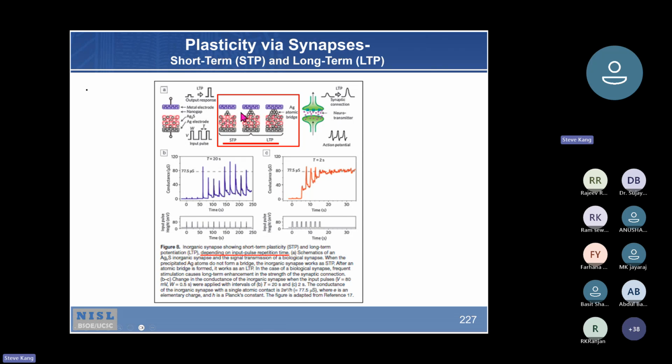And this graph shows a memristor, and whether your filament is fully connected, like here, or not connected, and then weakly connected, almost connected. So when it is in an unstable state here, it's short-term learning, short-term plasticity. And when it's fully connected, a very solid one, it's long-term plasticity. So this shows how you do that.